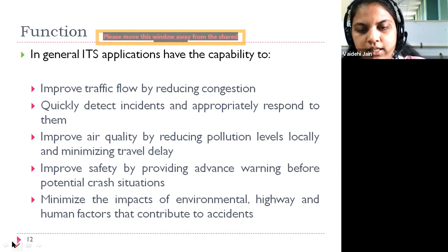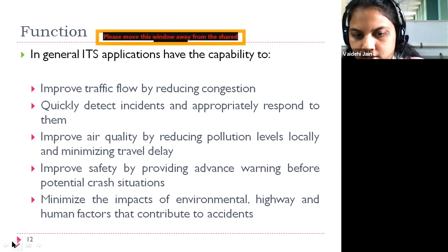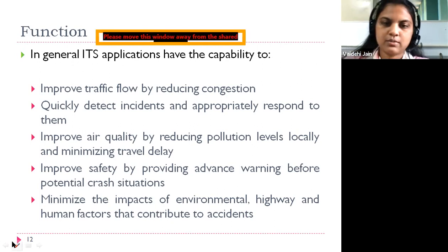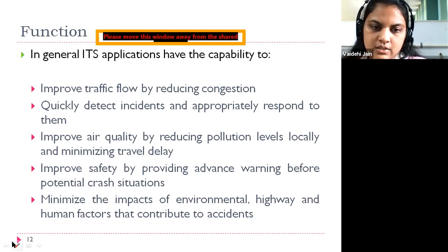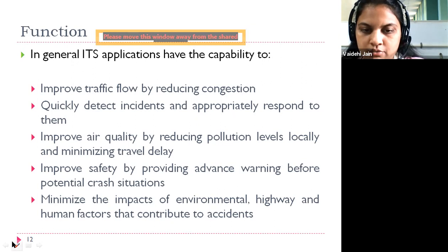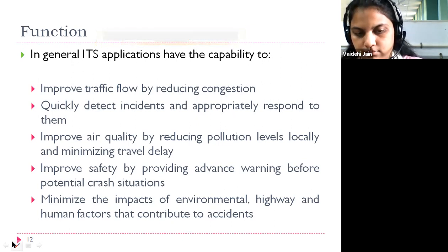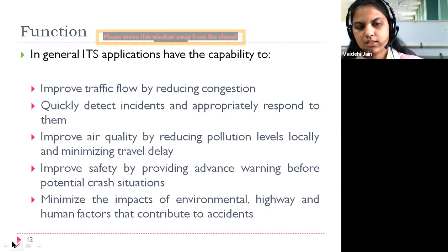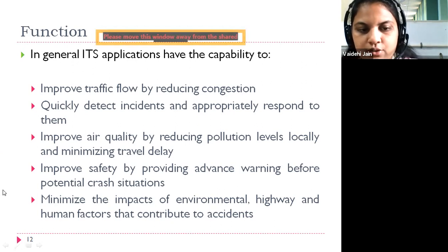Then improve the air quality by reducing the pollution level locally and minimizing the travel delay. What it means is, if the travel delays are there, more decelerations are there, queuing is there, then the pollution level will definitely increase. So if we can reduce the queuing process, or if we can reduce the delay process, then definitely we can improve the air quality.